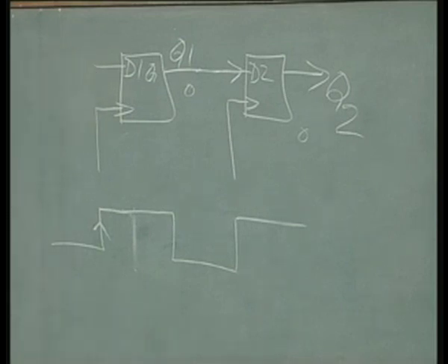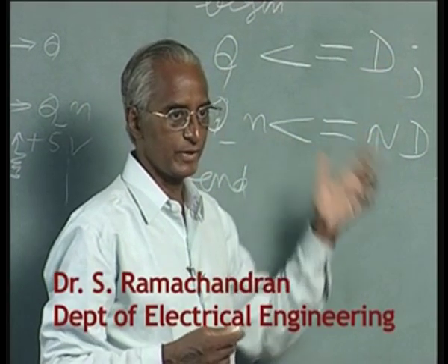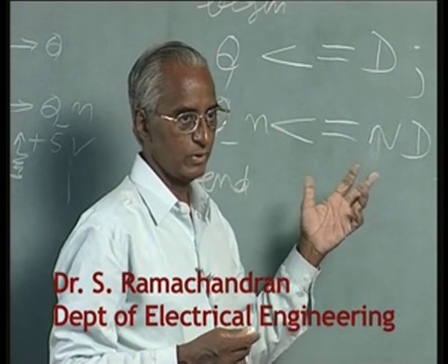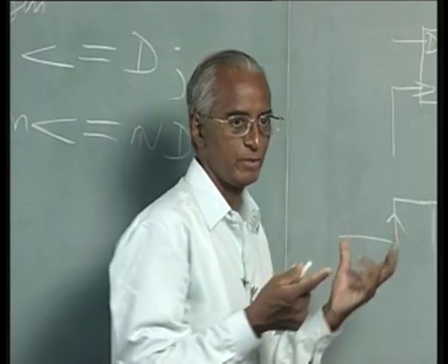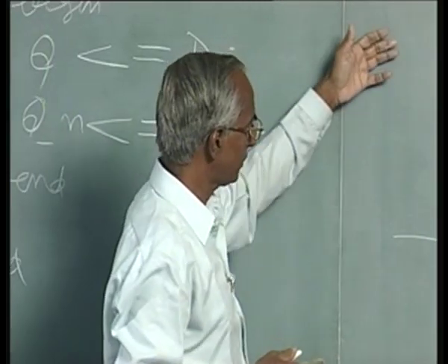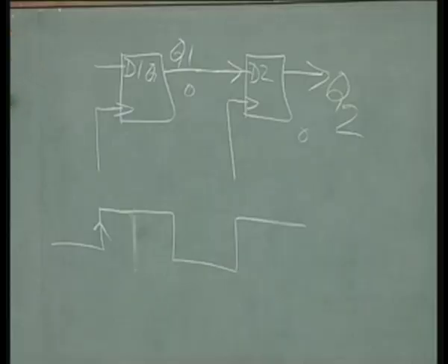We said ABC, and ABC is actually not the actual field inputs, it may be intermediate outputs which are fed back, maybe from a counter and so on. So the whole thing is synchronous as such. Wherever you have flip flops, all of them will be reset. So it is proper for us to assume even the ABC condition is also reset for the time being, right?